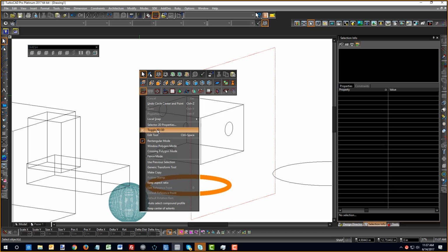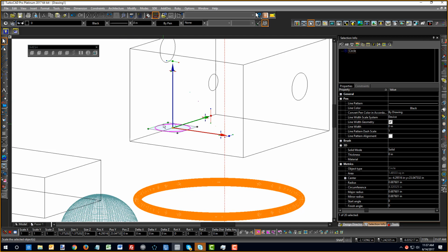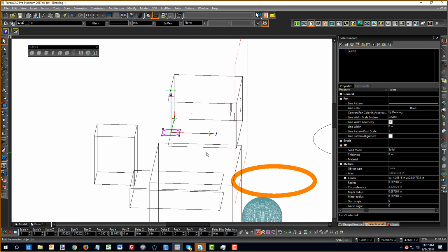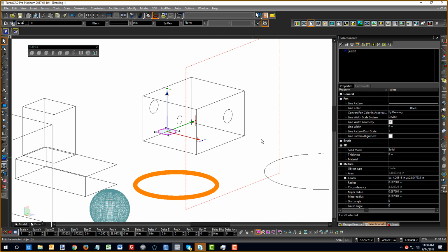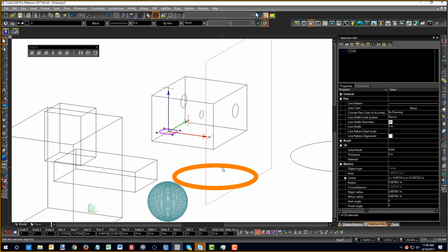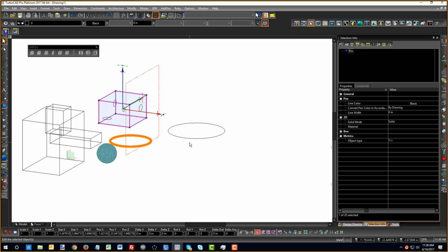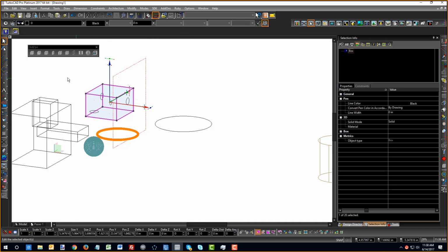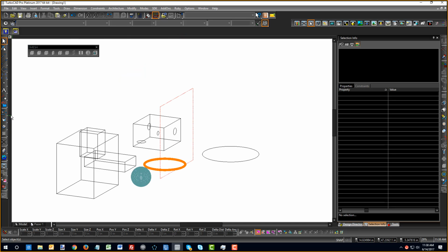The difference between the 2D selector mode and the 3D selector mode is this. So let me turn this back to the 3D selector mode. Now when I click on the circle on the world plane work plane, notice the work plane indicator stays on the side of the box, and that is because the 3D selector mode will not change the current work plane. So that is in fact where the most confusion when drawing in 3D occurs, in my opinion. Hopefully everybody understands that. If you need me to go over that again, we can certainly do that.